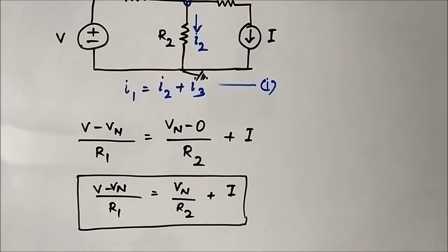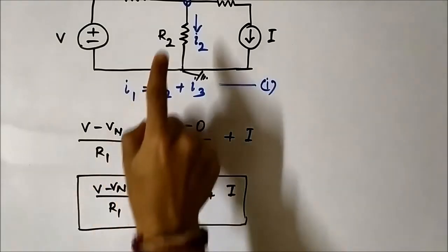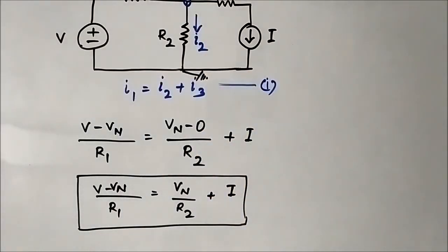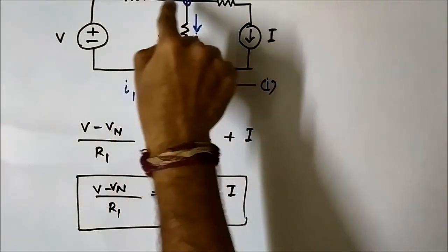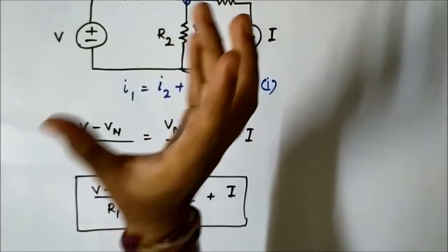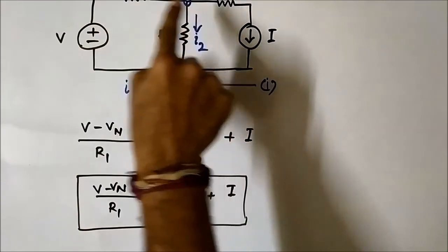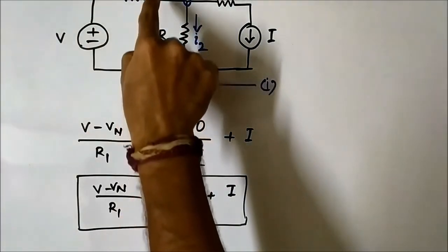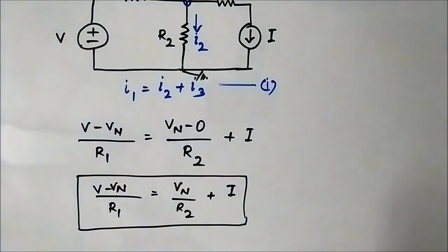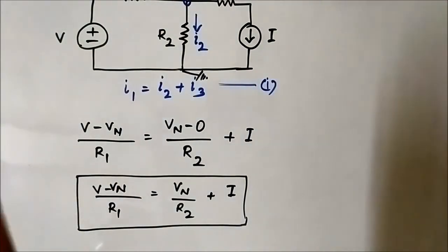So, you have to remember some basic points while applying nodal analysis. First, identification of the node points. A node is a meeting point of two or more circuit elements. Next, assign node voltages. Assign current values and directions arbitrarily as per your choice, but the restriction is that you have to write the nodal equations in the same way, following the same direction and convention. The current always flows from a higher potential to a lower potential, so you have to write the expressions of the assigned currents in the same way.